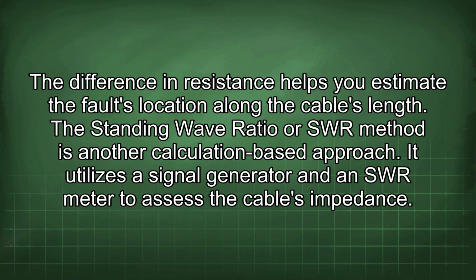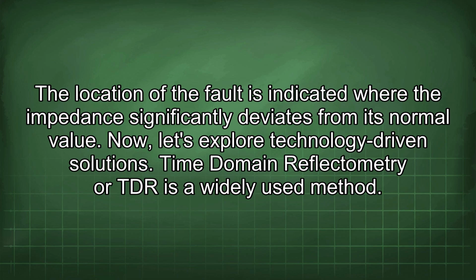The standing wave ratio, or SWR method, is another calculation-based approach. It utilizes a signal generator and an SWR meter to assess the cable's impedance. The location of the fault is indicated where the impedance significantly deviates from its normal value.